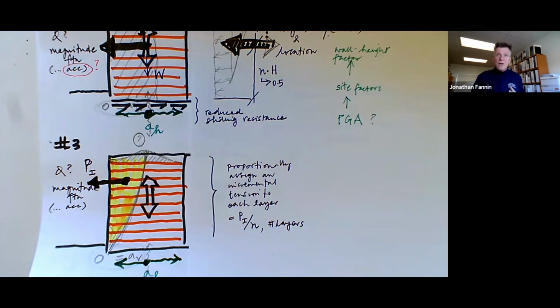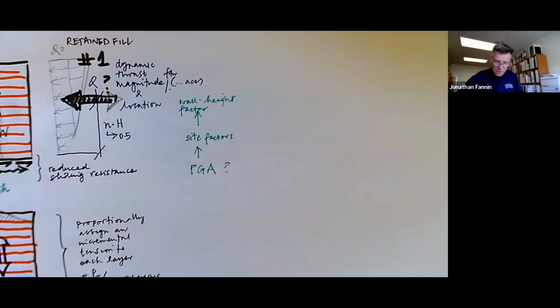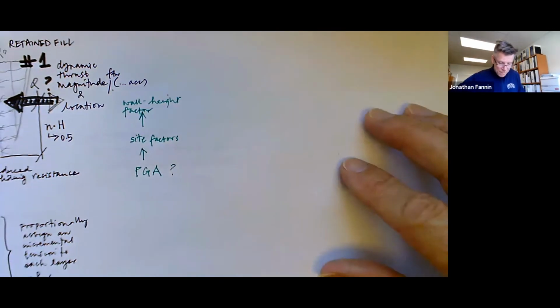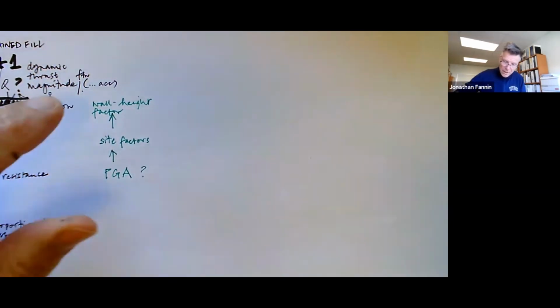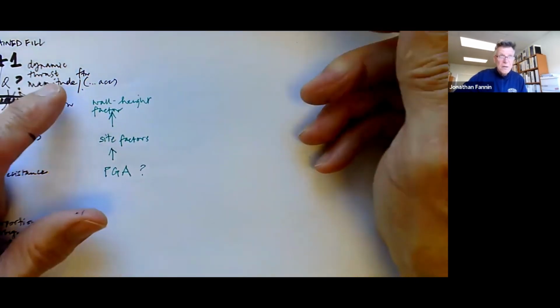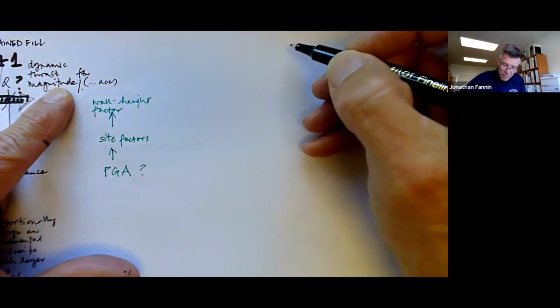And the most distress that I saw, and this was a take-home message personally, the most distress I saw on geosynthetic retaining walls was external stability failure, and external stability failure by sliding. And if I sketch it here, the worst case that I saw, the most dramatic, had displacements of maybe 25 centimeters to half a meter or so.